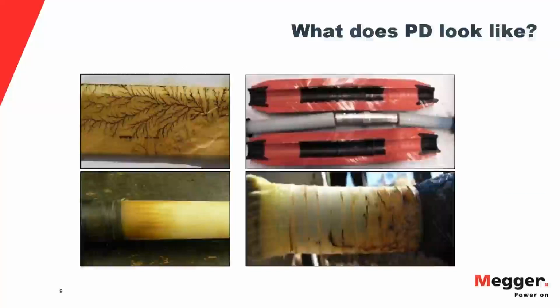What we see here on this slide is incomplete shrinking, where this whole area, I can highlight it with the pen, that's all experiencing partial discharge because there's an air gap up here. That wasn't completely shrunk. It's very common for the top of a heat shrink splice to be well treated, but the bottom is maybe a little bit harder to get to, and it might not be completely shrunk.